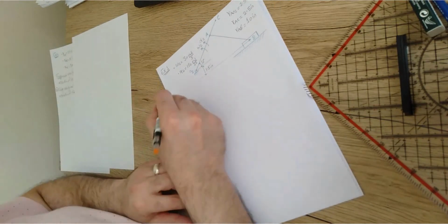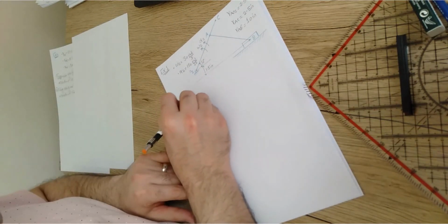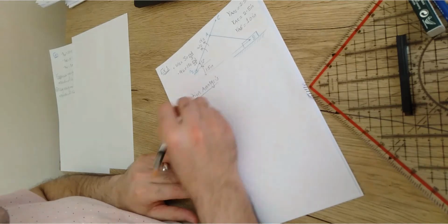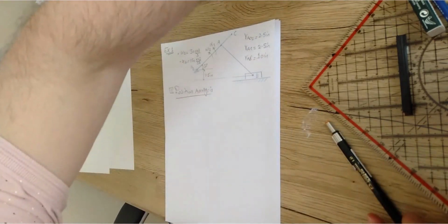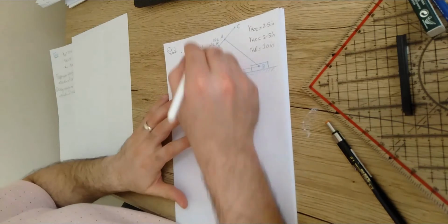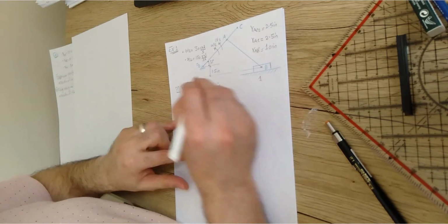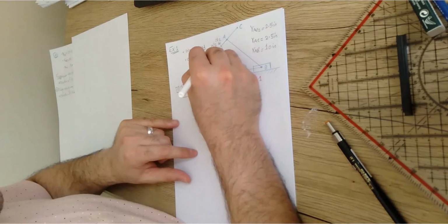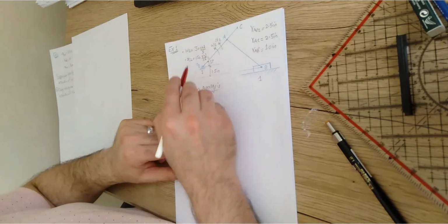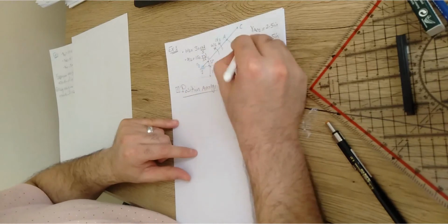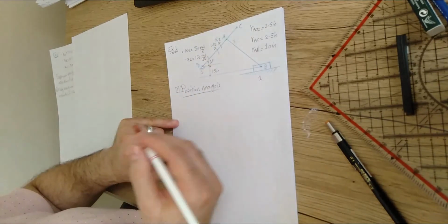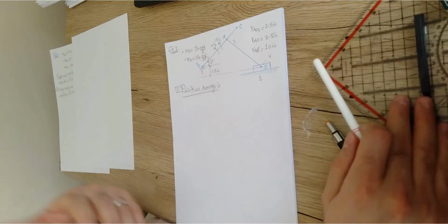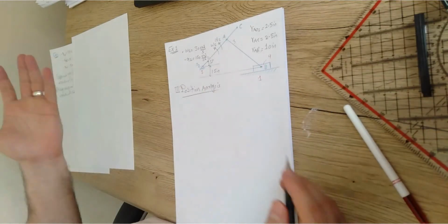So in the beginning, we're going to work as usual, and I'm going to start with the position analysis of the mechanism. As usual, the first step conventionally is just to give numbers to the different elements. So we do have the base or the ground, this is the frame, which is element 1. In addition, we have element 2, which is this link that rotates about O2. In addition to AB, this is link number 3, and element number 4, which is just a slider. So these are the 4 elements that we conventionally have for a crank slider mechanism.